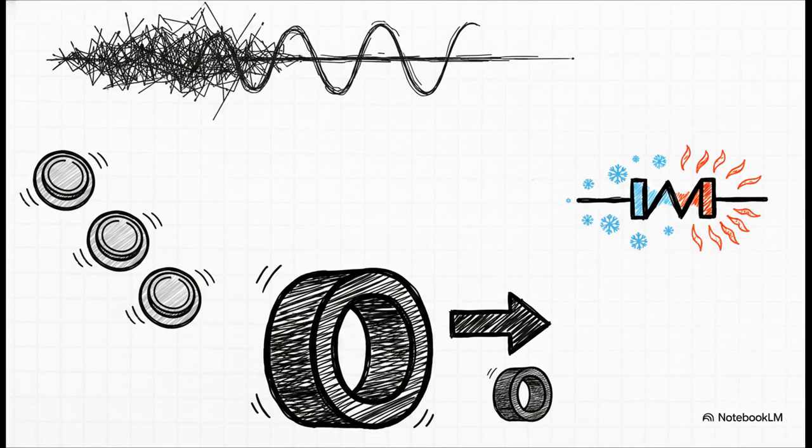And this brilliantly illustrates the variety of tools engineers have at their disposal today. We've got variable frequency drives, or VFDs, which control the actual frequency of the AC power to start a motor with almost zero current increase. In electronics, we use NTC thermistors. These are clever little resistors that have super high resistance when they're cold, which totally blocks the inrush spike. But as the current heats them up over a few seconds, their resistance drops to zero, letting normal current flow.